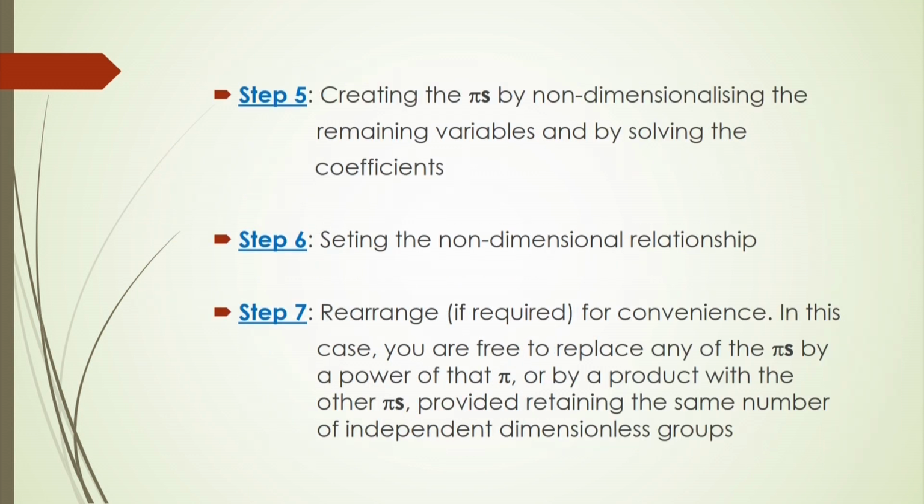And then step 5, you create the dimensionless groups as phis by non-dimensionalizing the remaining variables and by solving for the coefficients. And then step 6, you set the non-dimensional relationship, and in the last step you can arrange all these dimensionless groups for your convenience.